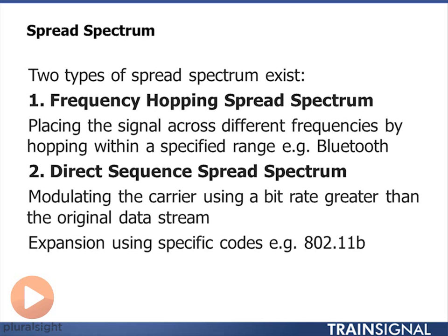Well, because if I transmit at a higher data rate, where each of those bits is at a lower power level, what will happen is my signal will spread, like we saw in the previous slide, across the band. And because I've applied these codes, I'm transmitting many, many more bits than your original information bit. And so if I lose a few of the bits because something's interfering, I can recover from it and I can still get back to your original bit. So it's a concept of applying codes and spreading the signal over the band.